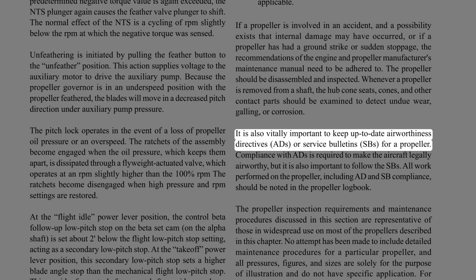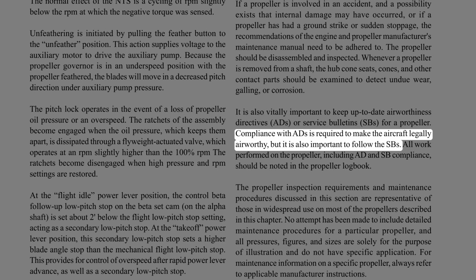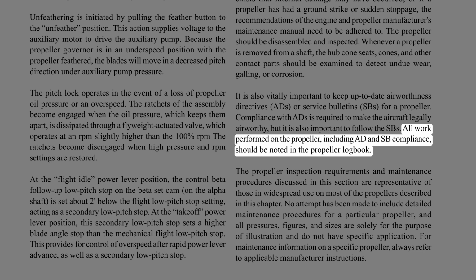It is also vitally important to keep up-to-date airworthiness directives, ADs, or service bulletins, SBs, for a propeller. Compliance with ADs is required to make the aircraft legally airworthy, but it is also important to follow the SBs. All work performed on the propeller, including AD and SB compliance, should be noted in the propeller logbook.